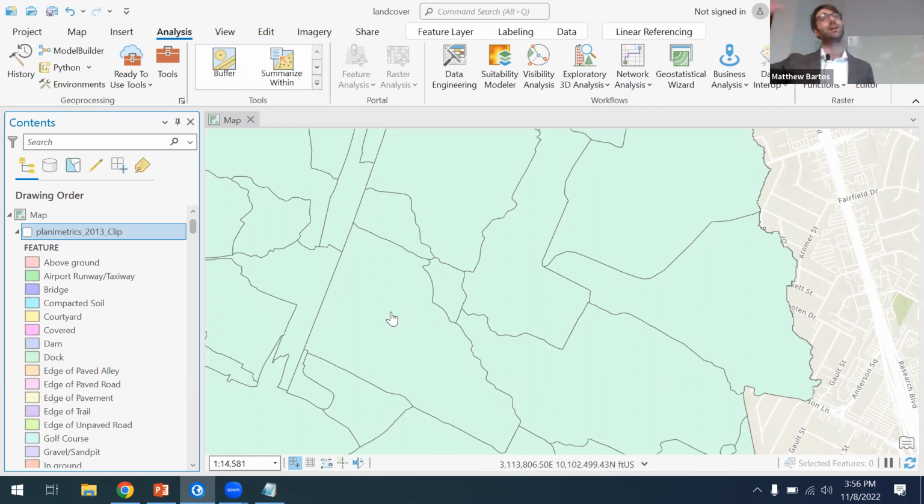So when you're figuring out how your land cover changes affect your flows, it's sometimes helpful to know what the land cover breakdown is within each subbasin and what changes to that land cover distribution have on the curve number, for instance, or the amount of depression storage or the amount of impervious area. So it can often be important to know specifically within each subbasin what the land cover breakdown is.